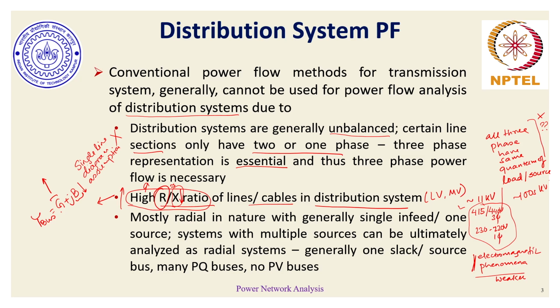Now, when the resistive component of the network tends to be dominant compared to the reactive component, the corresponding Jacobian matrices which we tend to evaluate, where for transmission network the diagonal entries are mostly significantly dependent upon the values of B and not so much on the value of G, because the sine of phase angle differences is more or less similar to the phase angle difference. The quantums remain the same. So therein the Jacobian matrix also starts to have some sort of deformity or an ill conditioning nature. That is not just one of the reasons why Jacobian tends to become significantly ill conditioned.